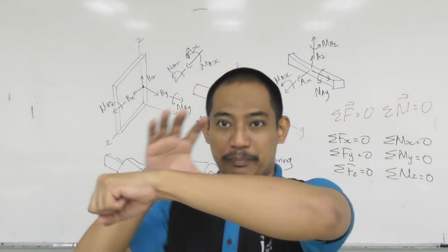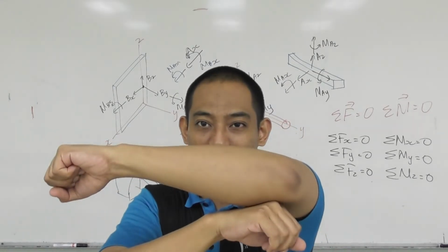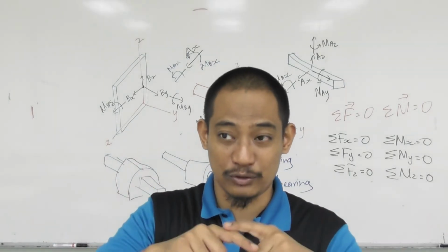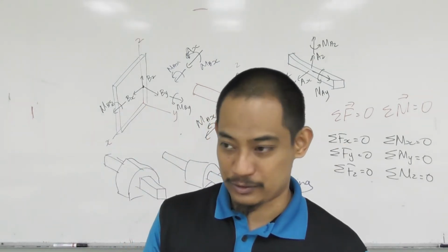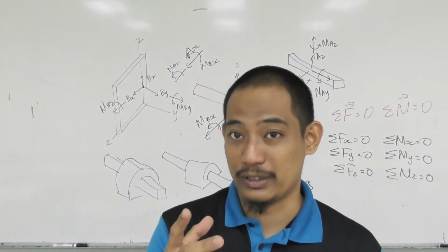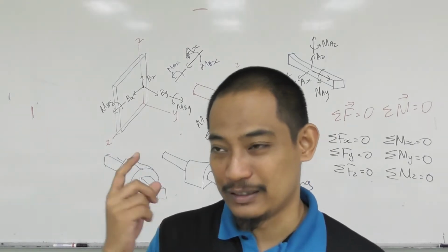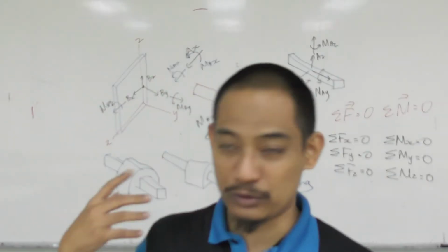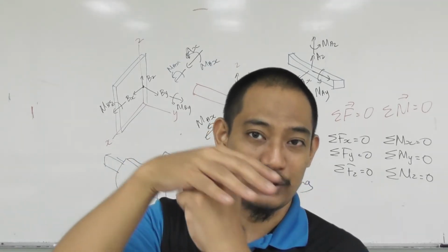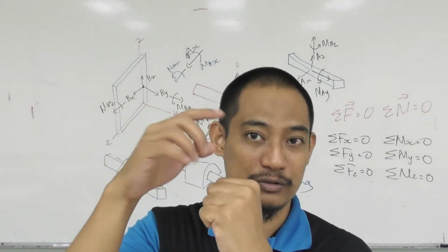But if you have, for example, a bearing here and then a ball and socket here, then you have 2 here, 3 here, etc., and the total should be 6, right? So we can test you on more supports. So that's normally what happens. When I say normally, it could be that suddenly a lecturer just wants to put in a fixed support. That should be easy normally, because you only have one point to consider and all the forces and moments.